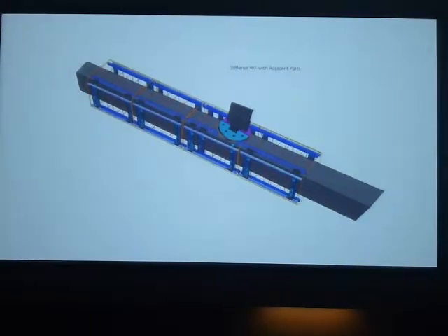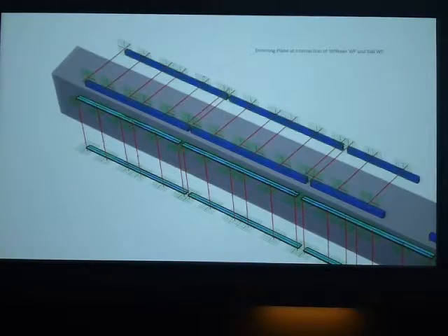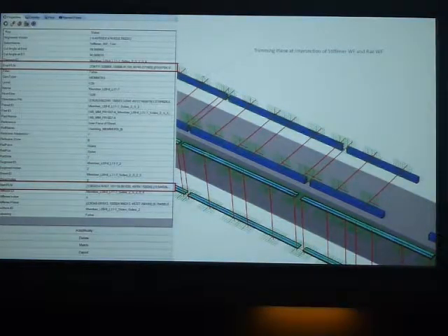These curves represent the nominal center line of the object at the top center. They do, however, at this point, not take into account the adjacent elements that they have to connect to. A Grasshopper session uses filtering of geometry by attributes and some one to few closest geometry lookups to find the connecting elements. Trimming planes will be derived from these elements and stored as attributes again inside the wireframe curve.